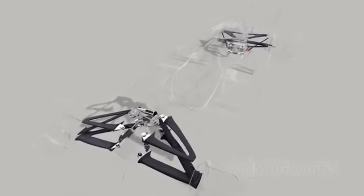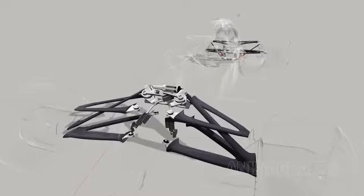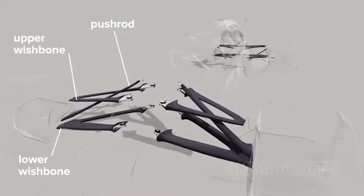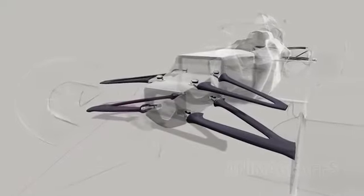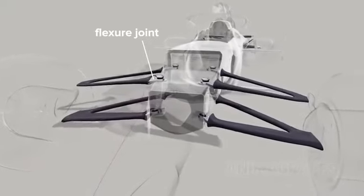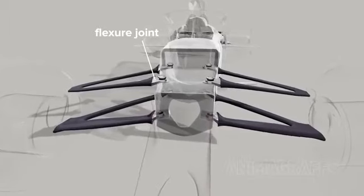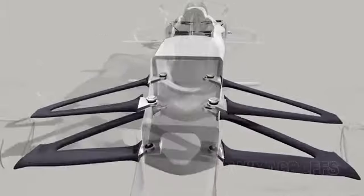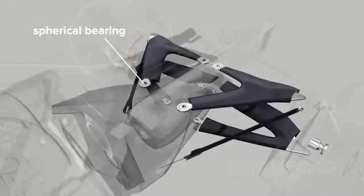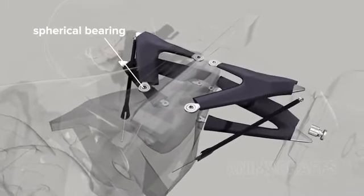Both front and back suspension setups share similar components: upper and lower wishbone arms with a push or pull rod. The wishbones are rigid structural supports with limited vertical travel. At the front, where heat isn't an issue, wishbones are directly attached to the monocoque and have simple flexure joints designed to bend under load. At the rear, where engine heat can be intense, spherical bearings are used.